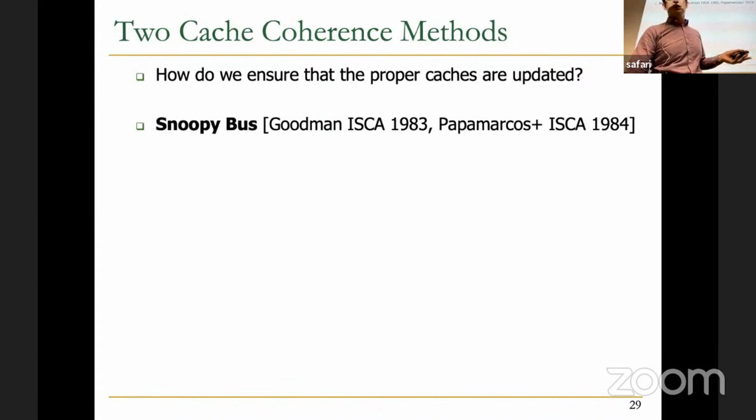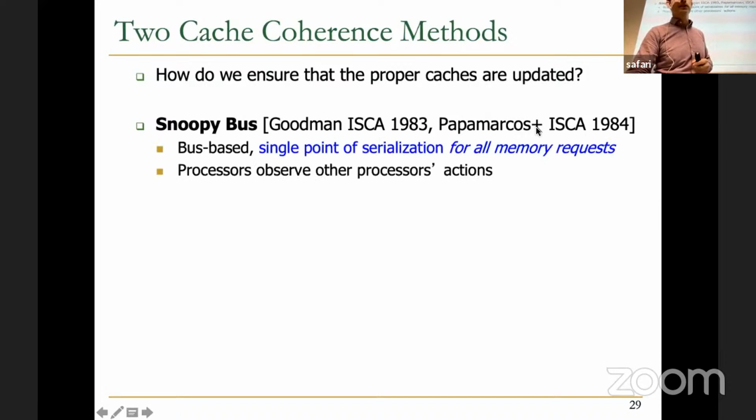Snoopy Bus Protocol was developed by these two major papers. I assigned the second one as a reading. It's actually very clean and nice. You can take a look at it. Basically, this is bus-based. It's assuming some sort of bus. And it's a single point of serialization for all memory requests. And that's essentially the bus. Processors observe each other's actions on the bus.